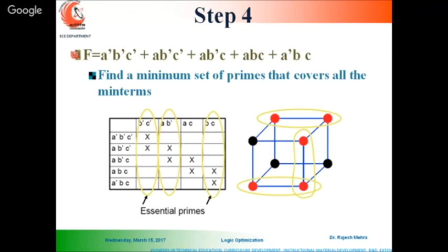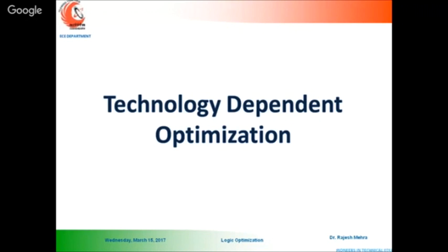Whenever you are performing it at the back end of your PC, some algorithm is running, and this algorithm is based on these different steps, right? So finally you get one structure that is optimal in terms of sum of product terms. You have reduced the number of sum terms and the number of product terms. Now you have one architecture. That will remain the same for all the vendors, as it is technology independent. Technology is not going to interfere in this.